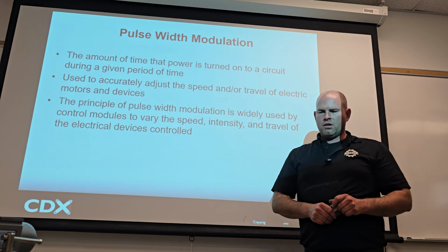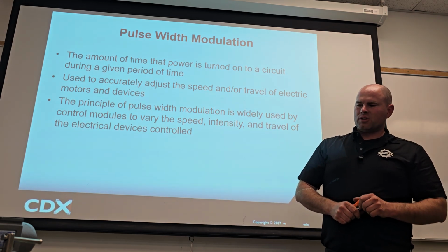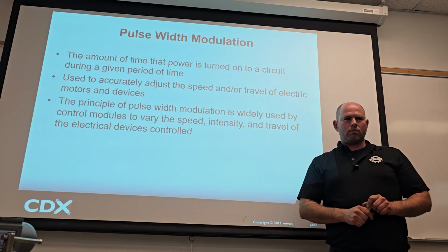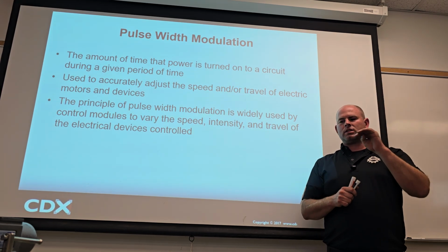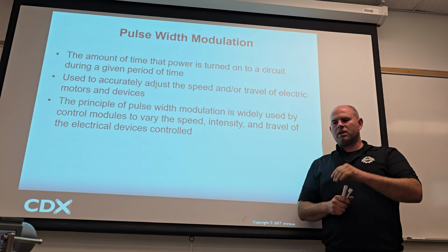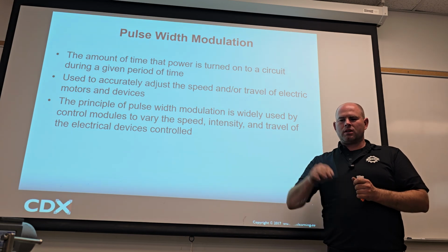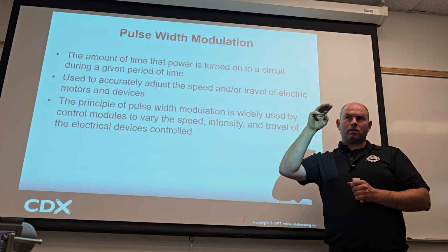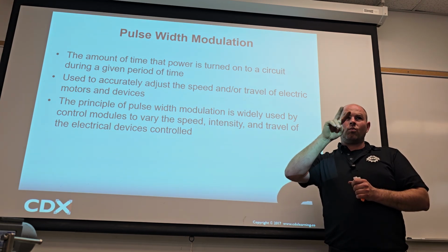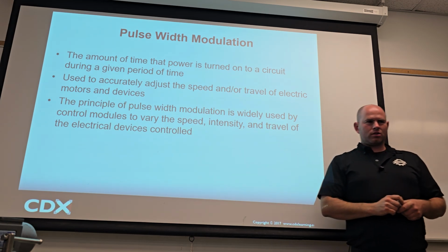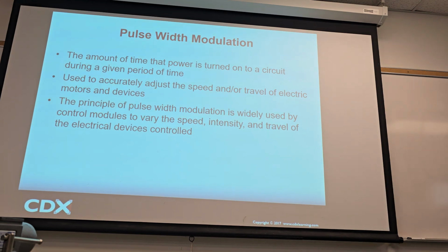Once in a while, for example, I had a fuel pump on one of my bikes that was giving me intermittent issues, and everything checked out with my meter. And then when I oscilloscoped it, I used the PicoScope, my favorite just because it's Windows based, there's 8 segments of the motor, and one segment was dead and one was half. But I couldn't see that with the meter. So if you're really going to do the diag, I would go right for the oscilloscope.